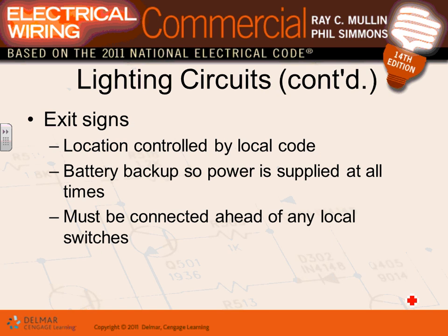Exit signs are a way of communicating with the public so they can safely exit your building upon an emergency condition. In an emergency, you need the public to evacuate your building, so they need to be able, without your direction, to find the exits. Life safety codes as well as building codes will force you to install these exit signs. Where do you need them? You need them on the egress path, wherever the egress path goes.